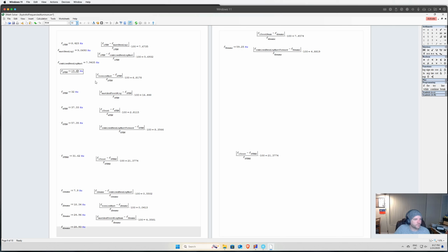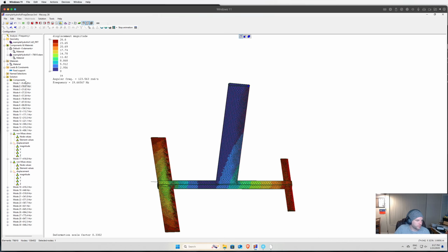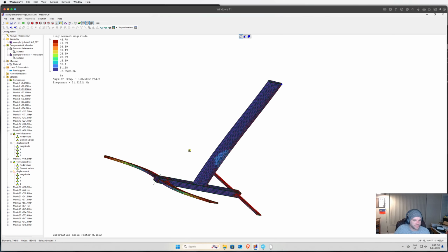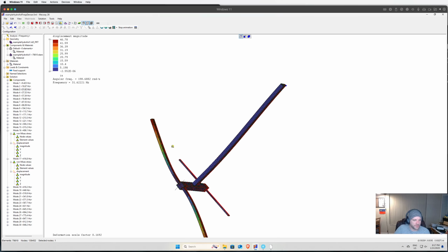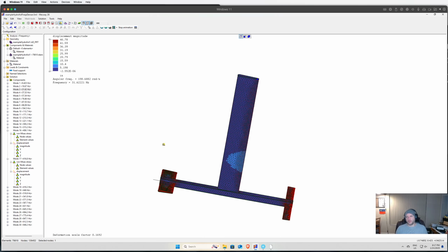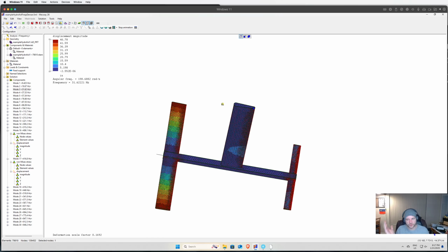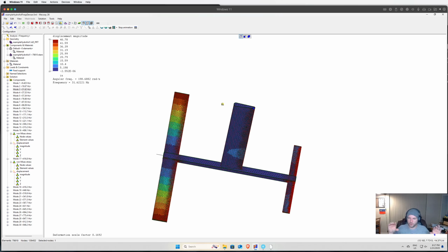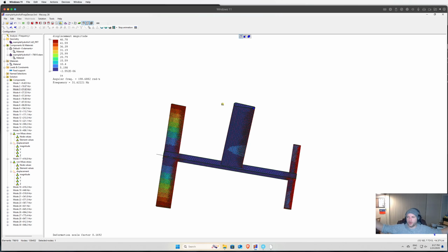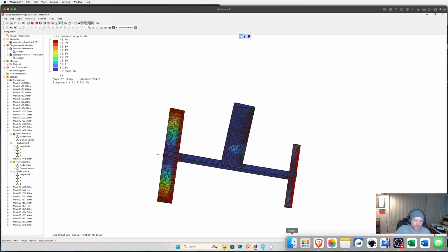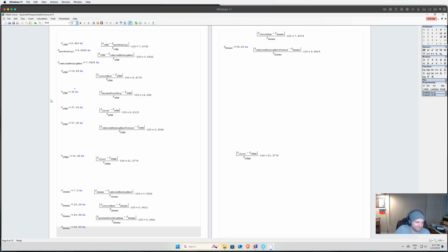So that's pretty good. And the first one, I think, showed the flapping of the wings, or just there we go. So there's this flapping of the wings mode, or twisting of the mast itself with the wings. And I don't think this is necessarily one of the first modes you see on a real hydrofoil. I think we are seeing this because this is a very simplified model. We have this thick piece of aluminum going all the way out for a meter. It's not tapering down, so you have a lot of mass out here, so it's actually causing the fuselage to twist around.